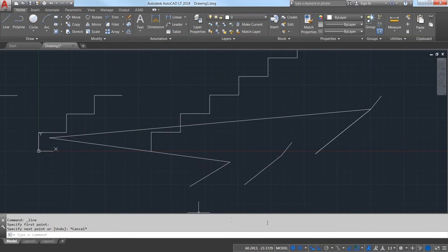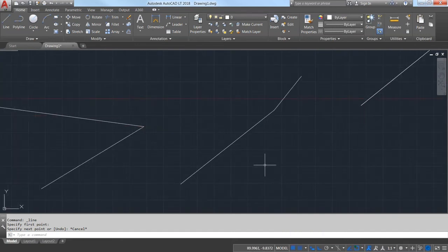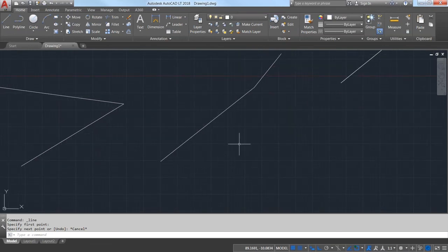F9, grid snap. Grid snap we didn't really get into much, but you notice with the grid turned on, you could potentially draw and snap your lines to the major and minor intervals of the drawing grid that's behind you in the background there. So you can see where that would be helpful if you were drawing something very precise and needed the grid points. You can also turn the grid display, instead of lines, into just individual points at the corners of the grid, instead of having grid lines everywhere. So it just depends on your preference what you want it to look and feel like.